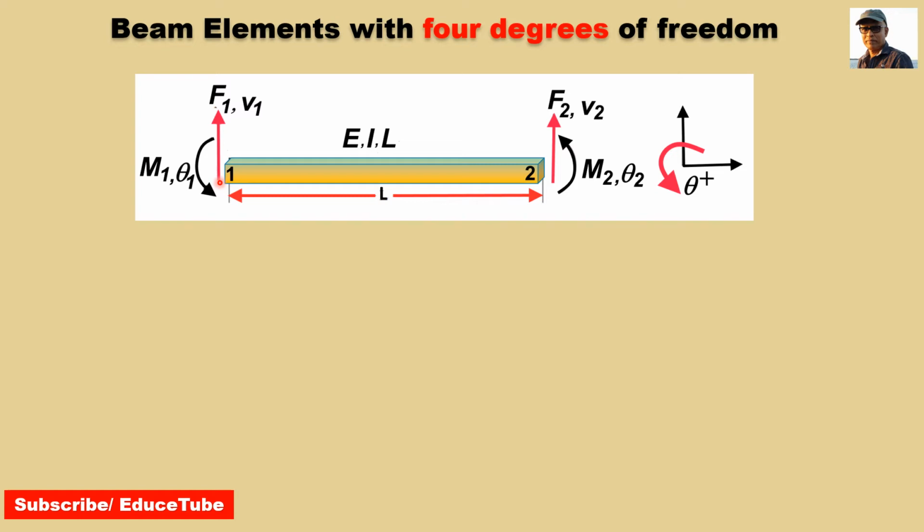And due to that, the beam suffers nodal displacement. That's why I put here nu1 and nu2 as the displacements. And also it suffers rotation theta 1 and theta 2. One important point is I did not include any axial forces on this beam. So we can say that axial forces are assumed to be equal to 0.